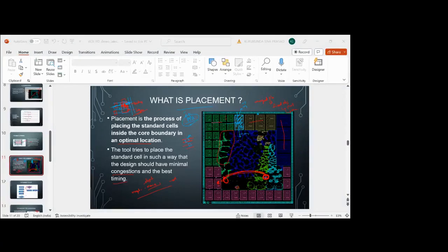So based on the slack values, we have to give the weight, right? Or is there any other deciding factor? Based on the slack is one thing. For example, if the same endpoint was repeating multiple times, with different start points, say 100 start points and one endpoint, then in this case also you can give high weightage, even though the slack was less.